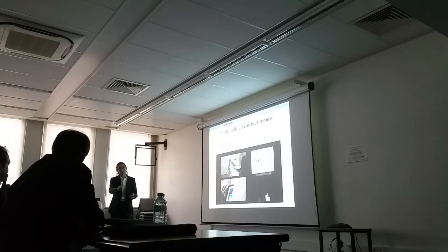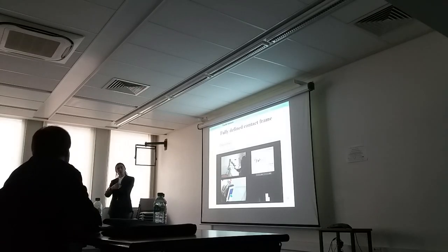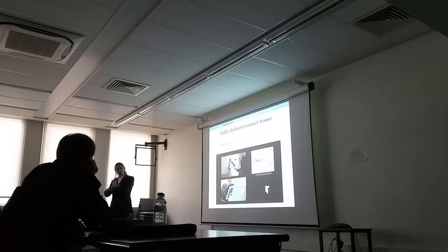When a robot is pushing some object and then sees the response, it can learn what actions can be performed on it, or which consequences they lead to. Or, we can measure the torques of a robot arm and push some static environment with the tactile sensors, and then do online calibration based on the torques we apply, and estimate the force applied at the end effector.